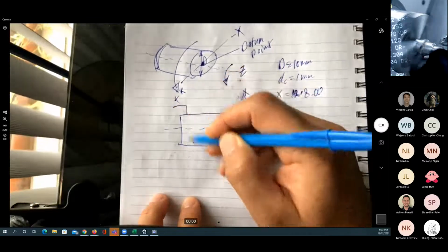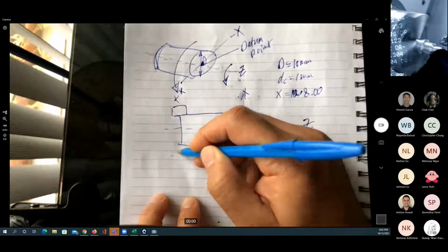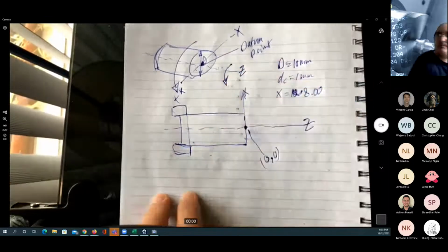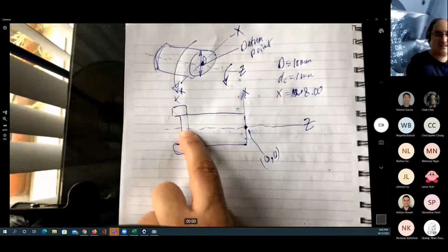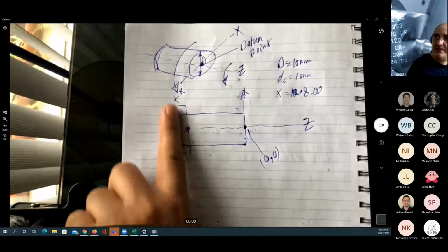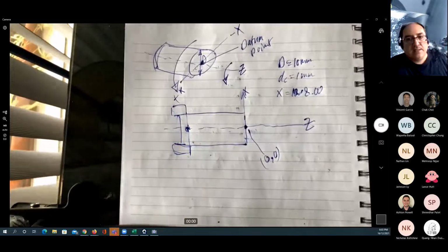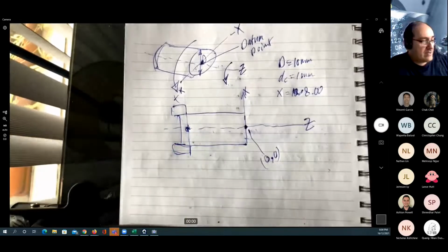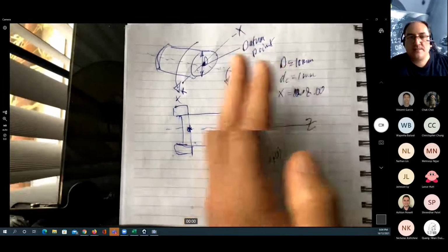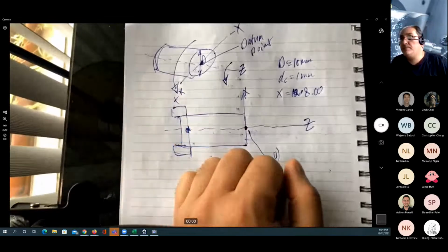The spindle holds the part by using the chuck. As I told you, some people prefer to have this point, which is exactly at the end of the chuck, as a datum point. They think it will be much easier to have all the z values positive instead of calculating in negative. It's a good point of view.